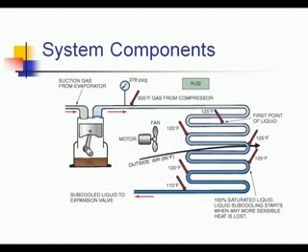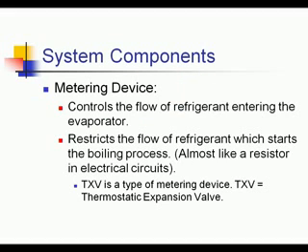The next step in the refrigeration process is the condenser. It rejects the heat from the system. It condenses high pressure vapor into high pressure liquid refrigerant at approximately 30 degrees above the ambient temperature. In this case, we're getting our suction gas from the evaporator. We're coming through the compressor and we're discharging it at 278 psi, which is 200 degrees.